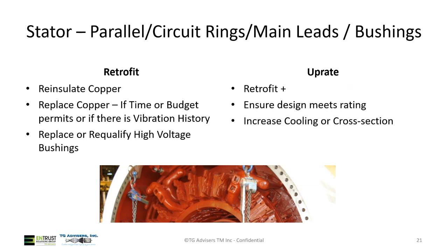But if you don't notice the dusting and greasing before you go to do the rewind, and it just gets re-insulated and put back in place, that fatigue may already be there. And if those components fail, it's typically catastrophic. At least that end of the generator takes a lot of damage.